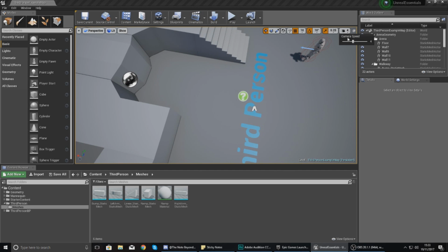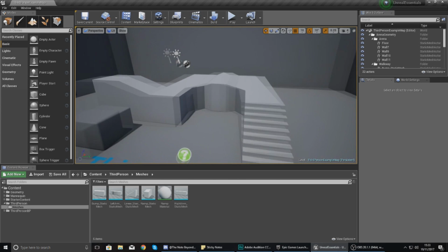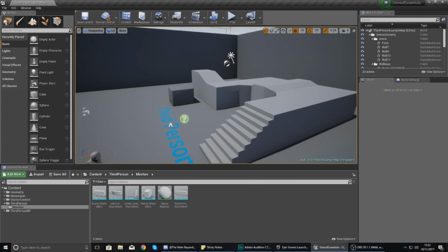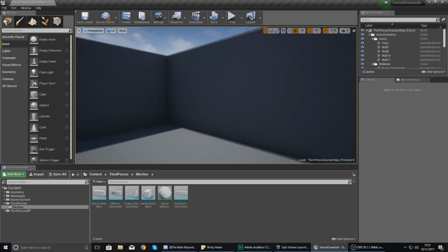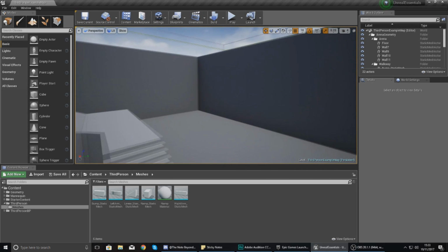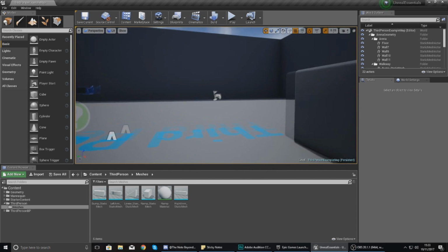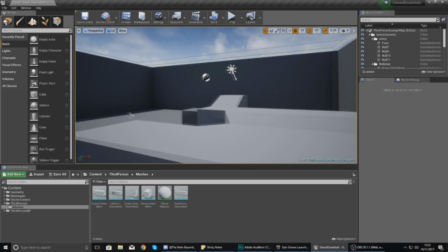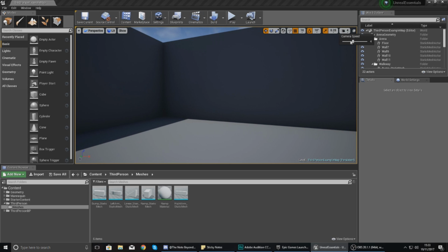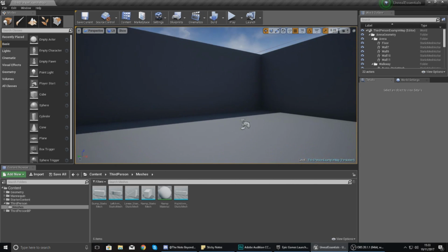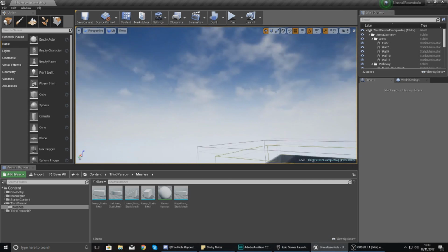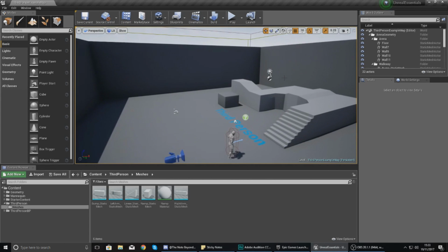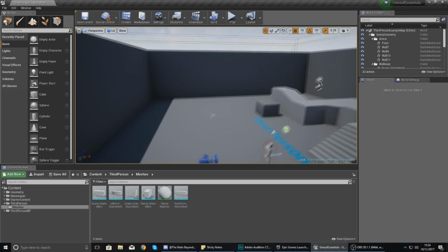Now, you can actually adjust this. I'm going to quickly change this back to 4 so we have a half decent speed, but you can actually adjust this while you're moving within your viewport. So if you're going in like this, if you want to, you can use the scroll wheel and scroll up. You can use the scroll up and the scroll down to speed things up and go a little bit faster. So instead of stopping, changing the camera speed, you can just use the scroll wheel to do it. So you can see I've got a decent speed here. And then if I speed up by scrolling up, I'm now suddenly moving really fast. And one thing I do want you to note is that this is completely independent of your camera speed at the top here.